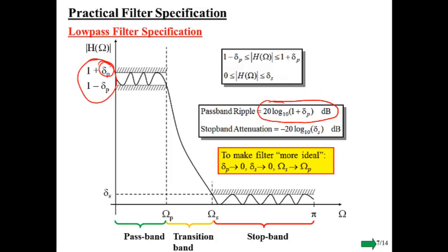That's called our passband ripple, and if we convert it into dB like that, we would be talking about how much ripple up and down in decibels we would be seeking for our design. It's not uncommon to see things like 1 dB of ripple, or even less, maybe 0.5 dB for a really good filter, 0.1 dB for a really good filter.